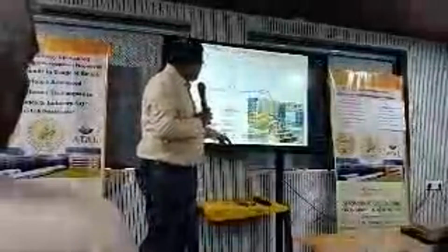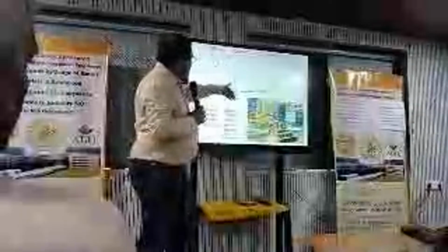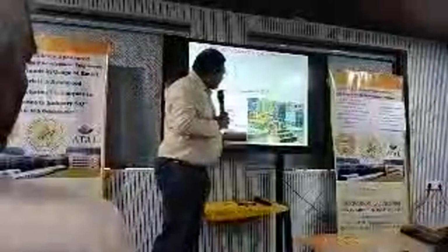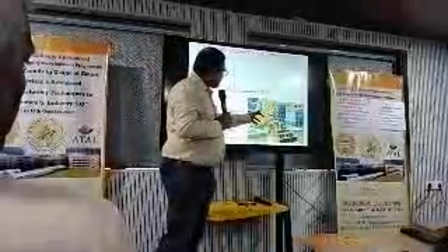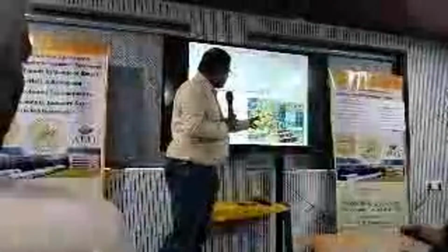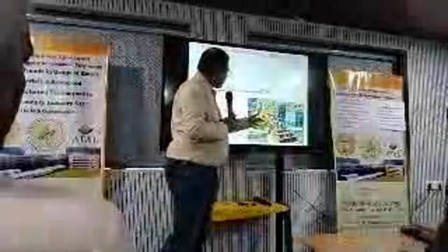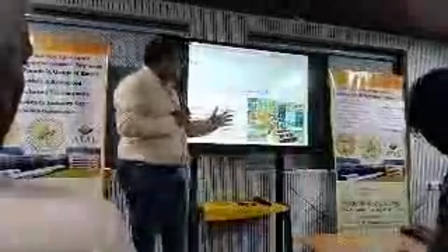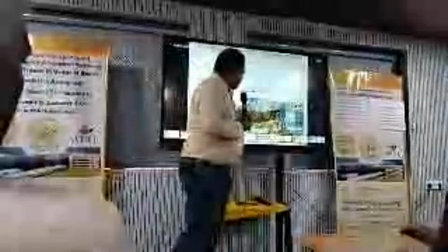So the same TMDs we have developed, and all these peaks we have reduced drastically. The TMDs we can assemble in all three directions X, Y, Z and at all the 4 places. One is the vertical direction, the horizontal direction, and the lateral direction. Like at all the 4 places we can apply, 1, 2, 3, 4, small ones. Finally, these vibration levels we can reduce.